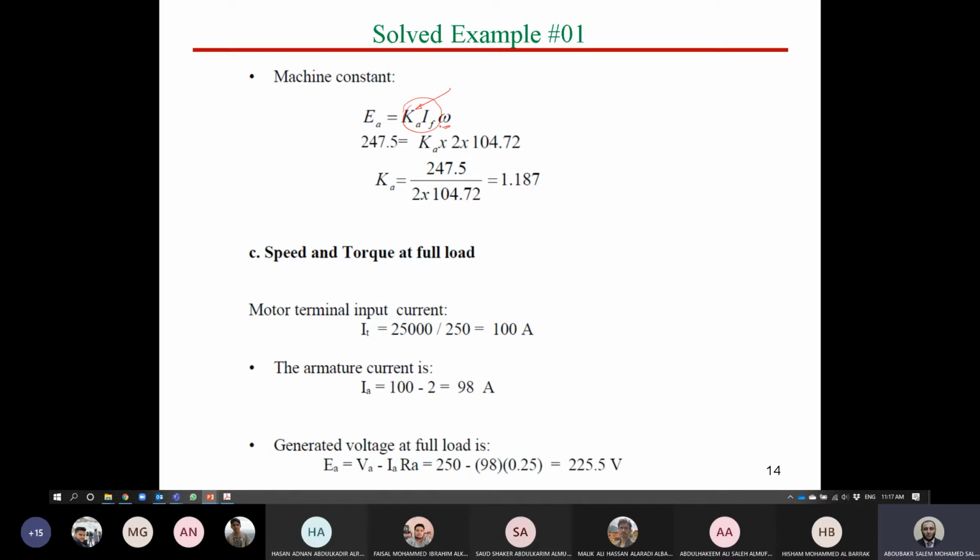As you can see, we get Ka from omega. So it's now in the units of the motor constant here. We can say it's volt divided by current multiplied by radian per second. So it's volt second over ampere radian, like that. Okay. Sometimes you can calculate the motor constant as a function of RPM. It's possible. However, when you multiply by speed, you should multiply by RPM. And take care about your calculations, and you can get it as a function of RPM or radian per second. However, you have to use it in the right way.